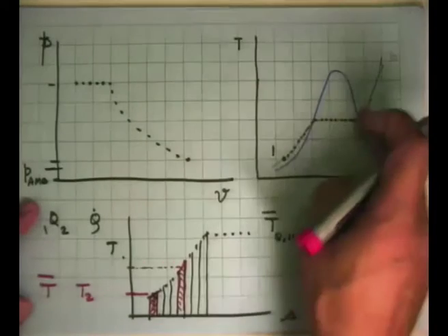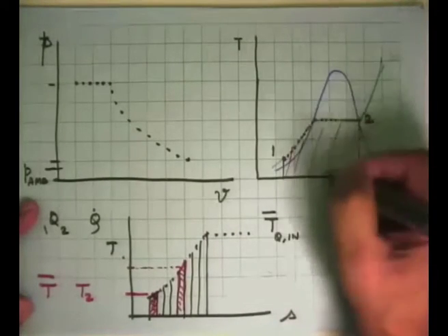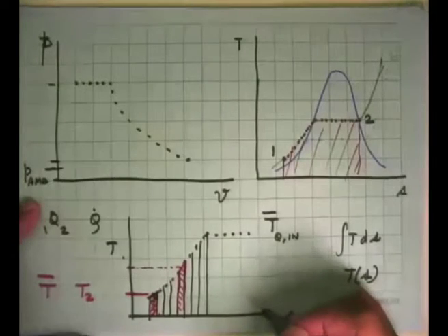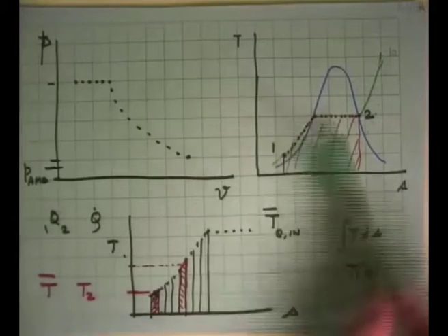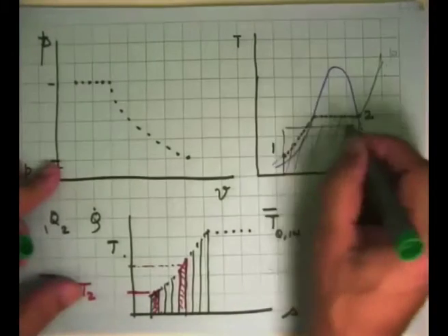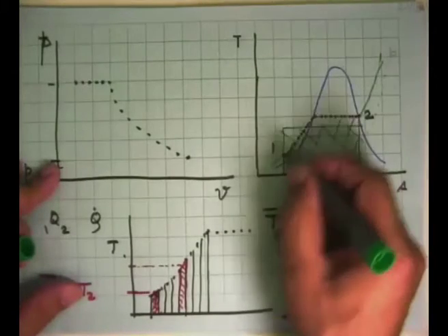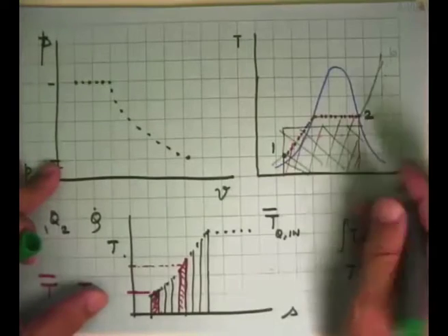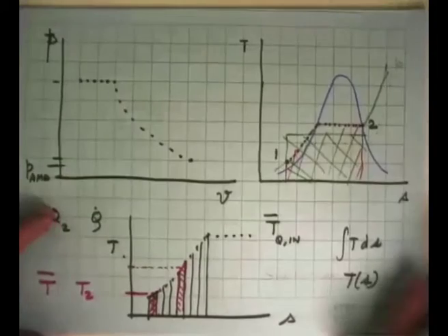And then we say, well, what is the total heat that we added in this process, which is this much. If I have to say what is the average temperature at which we added this heat, then I can approximate this area by a rectangle which is like this, which has the same area as the area under that curve. So this area and that area are equal, that means the same amount of heat was added.